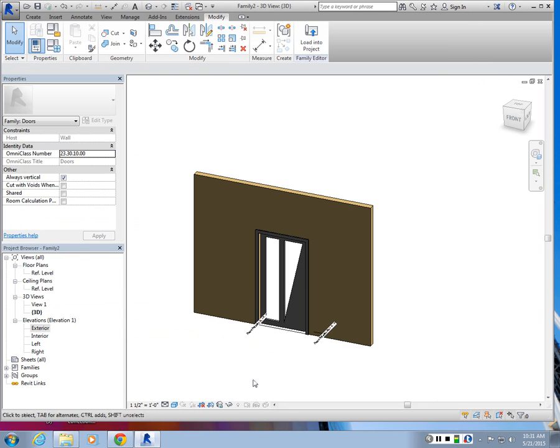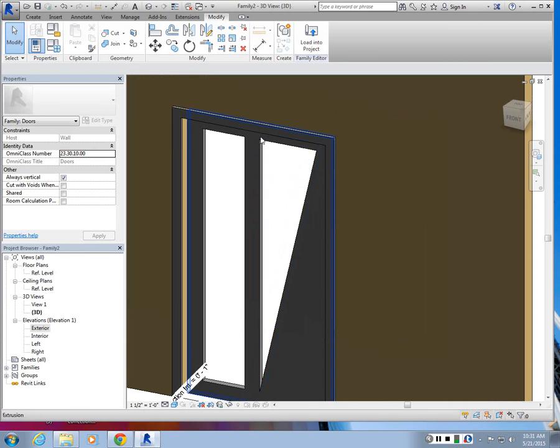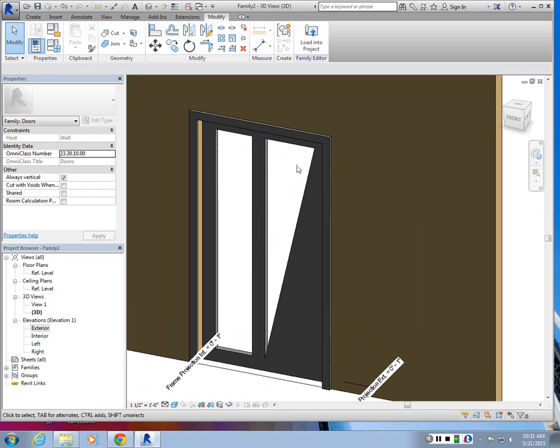So the problem was, in order to do the void extrusion in elevation, it just does the extrusion, but it doesn't automatically subtract the form. So to get that to work, I had to do a cut. So you select cut, you choose the solid frame, and then choose the void form to subtract it to get that to work. Okay, that was the issue I was having.